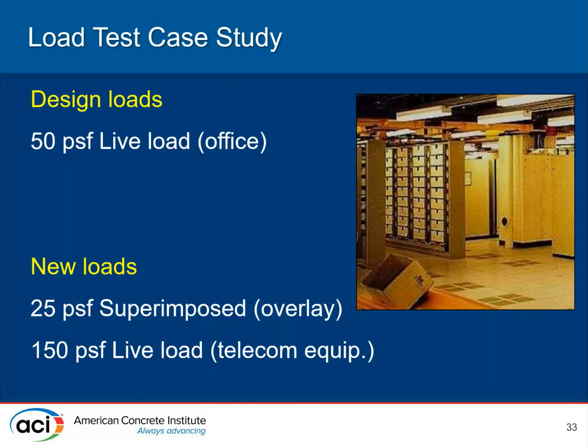This particular example highlights the current office load, which was 50 pounds per square foot live load, but then was evaluating potentially new loads: a 25 PSF superimposed overlay, and also 150 pounds per square foot live load. So extensive additional loads on the structure compared to the original.